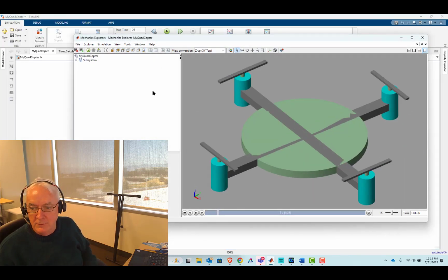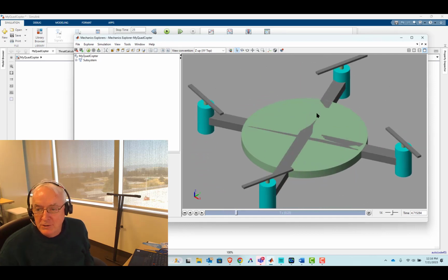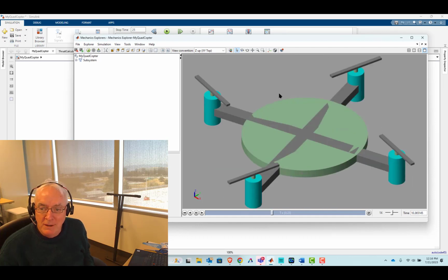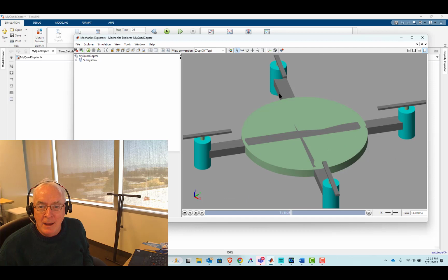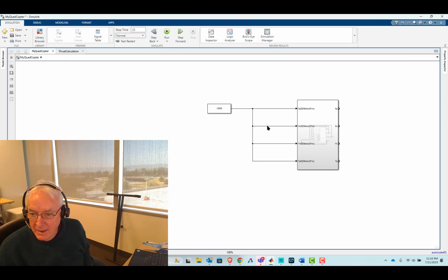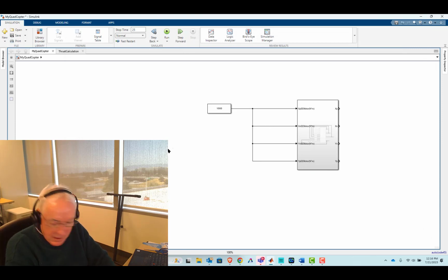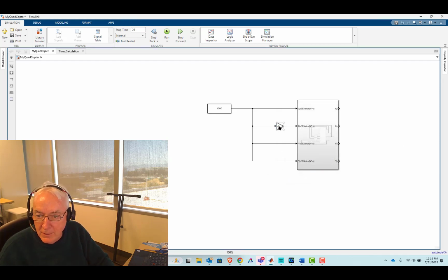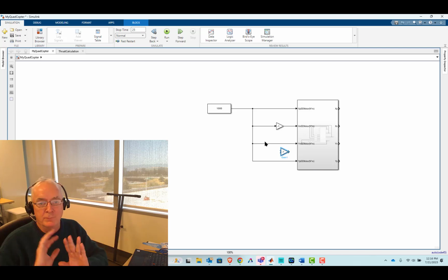But you'll recall we took on one problem early: if you're spinning all the propellers in the same direction, then for angular momentum to be conserved, the whole vehicle will have to spin in the opposite direction. Kind of a cool thing to revisit. Our previous solution was to take a gain and make it equal to -1, on each of the ones at the negative end of the beam. At the time, I thought it was a good idea. That's actually a really dumb idea.